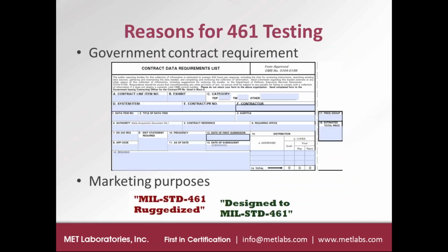So typically MIL Standard 461 testing is performed for one of two reasons. Most often it's part of a government contract where some department of the U.S. military puts out a request for bid to build an electrical or electronic device, and different contractors will bid on that. And as a contract requirement, often MIL Standard 461 testing is required, and a compliant test report needs to be delivered as a part of that contract.